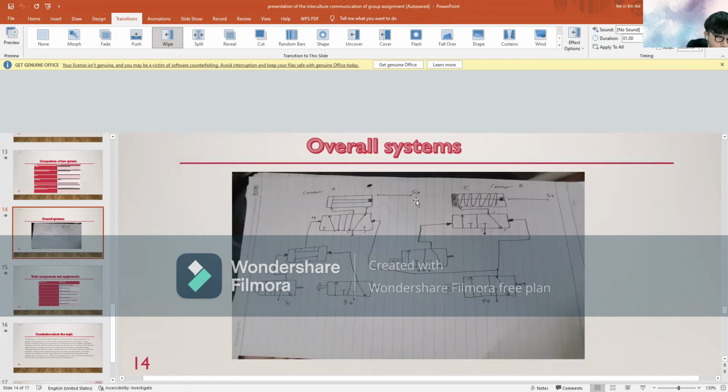And when the piston of conveyor A touches S3, which is the roller and acts as a sensor, the sensor will sense it and push the 3/2-way directional control valve, so that the inlet port will have the air source to push the single acting cylinder piston to the advanced position.